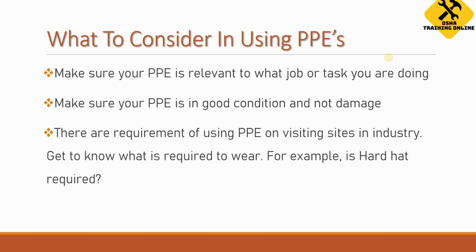You are working in a noisy situation where there is huge noise in the industry. In that case, you should use earmuff PPE. So it depends on what kind of job or task you are doing, and according to it, you should use your PPEs. For example, there is no need of using hard shoes if the situation is not slippery and there is no chemical spillage. In that case, you do not need to wear hard shoes.